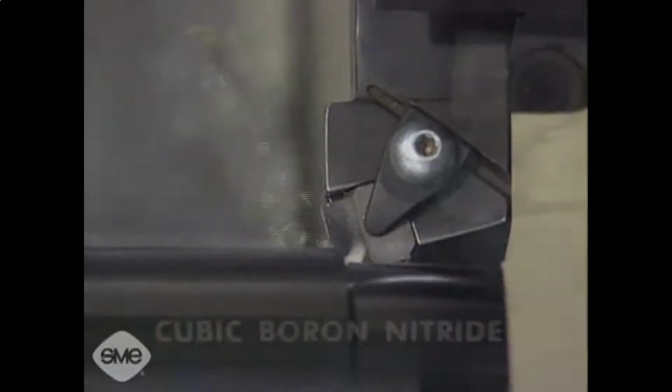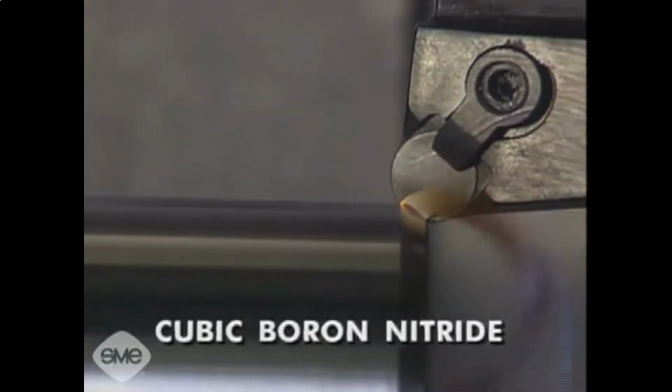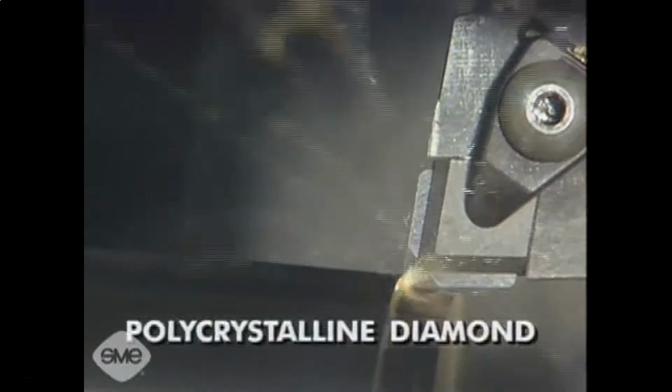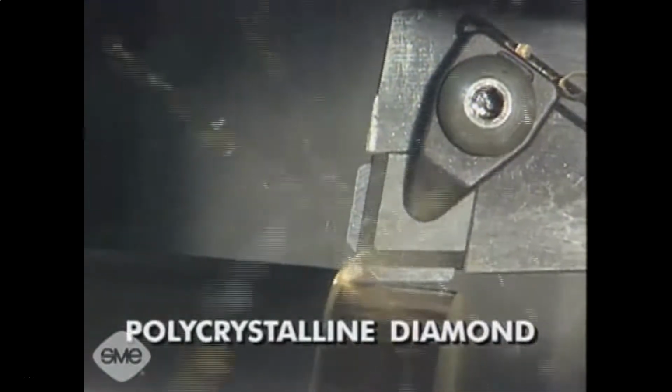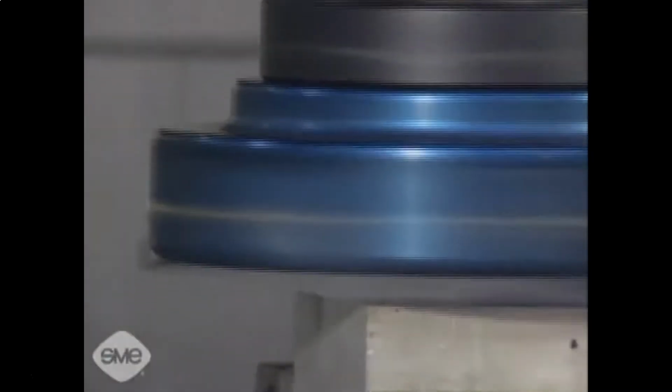But cermets do not withstand high heat well. The super hard materials are cubic boron nitride, CBN, for ferrous applications, and polycrystalline diamond, or PCD, for non-ferrous applications. Both materials are expensive, but can outlast carbides by 10 to 100 times.